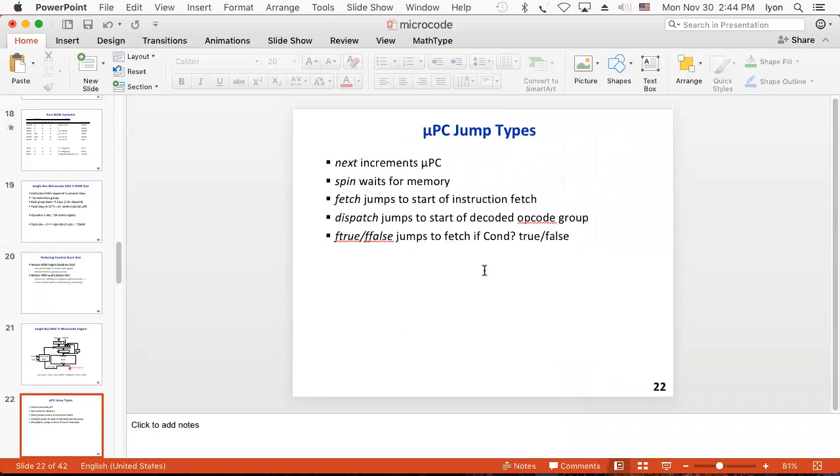A lot of times you create a read-only memory that reads out a next address, and that gets jam loaded into your program counter. Then if you want to jump to that next address, you use the loop inside of the finite state machine to retrieve the program counter's address and use that to look into the memory and get the next operational code.